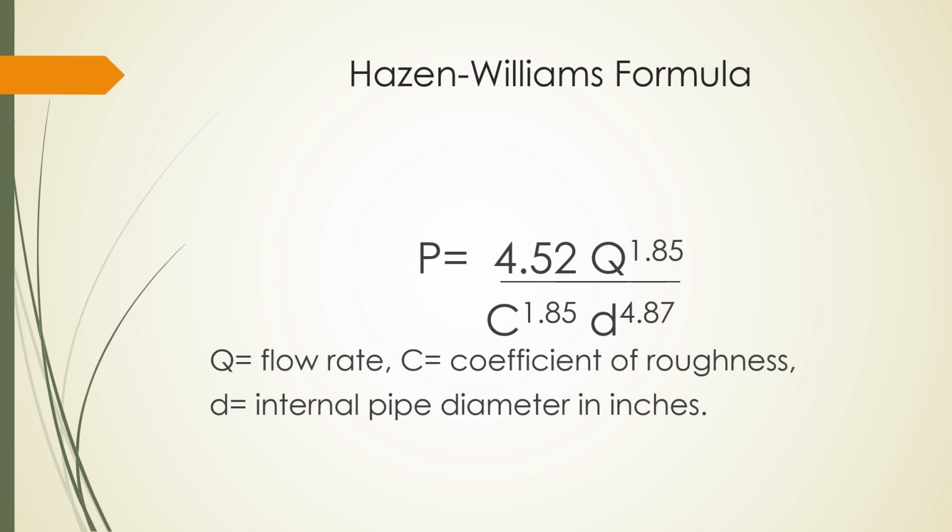The C is, of course, an unknown, to be quite frank with you. I would just say to play it safe, use the numbers that have been established by NFPA: 120 for the wet, 100 for the dry, and 100 for the underground if it's other than plastic. Don't try to be coy and don't try to be cute. The actual C is probably not those numbers, but as long as you use what the code provides you, then you're probably in the best position.